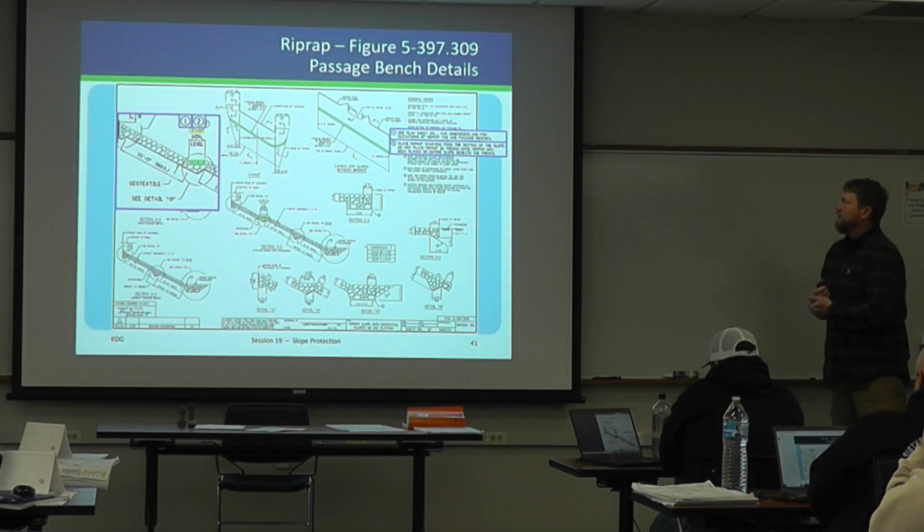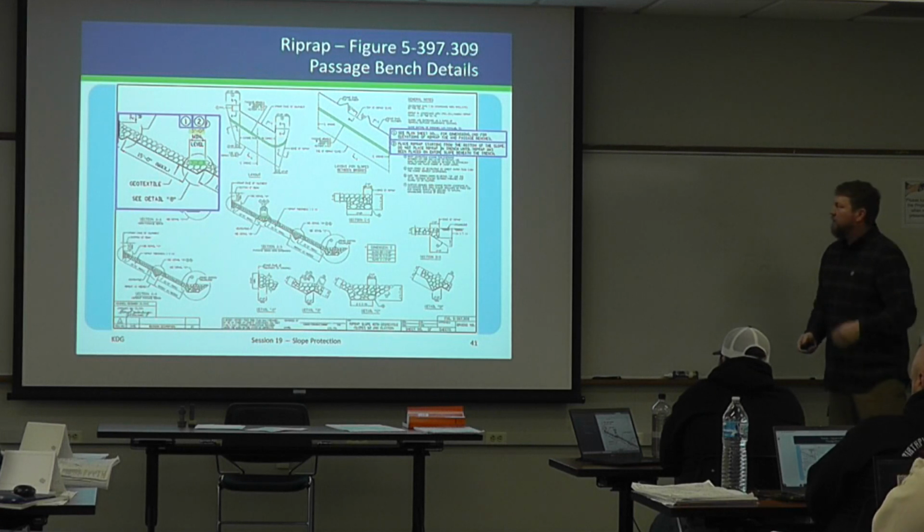This note talks about starting from the bottom and working your way up, and not placing riprap in the trench before everything up to that point is placed. Just kind of common sense.